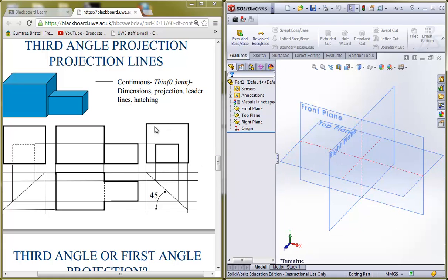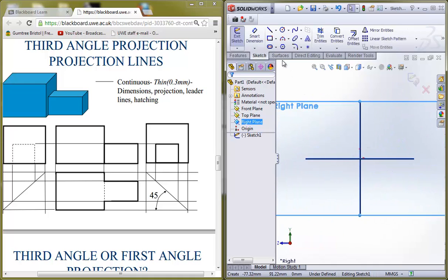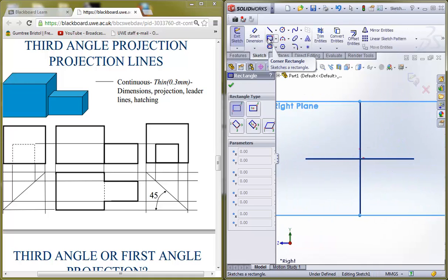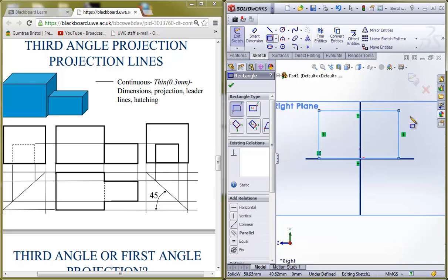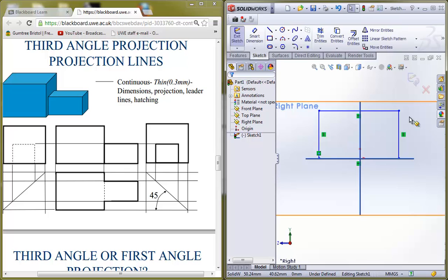I'm going to sketch this rectangle, and I'm going to create another rectangle on the inside. Well, let's just go ahead and create ourselves a little sketch on the right plane using a corner to corner rectangle. Once we are in the tool, I'm going to start drawing from the floor plane up. I'm going to select and click again to confirm. Press escape to come out of the rectangle tool.